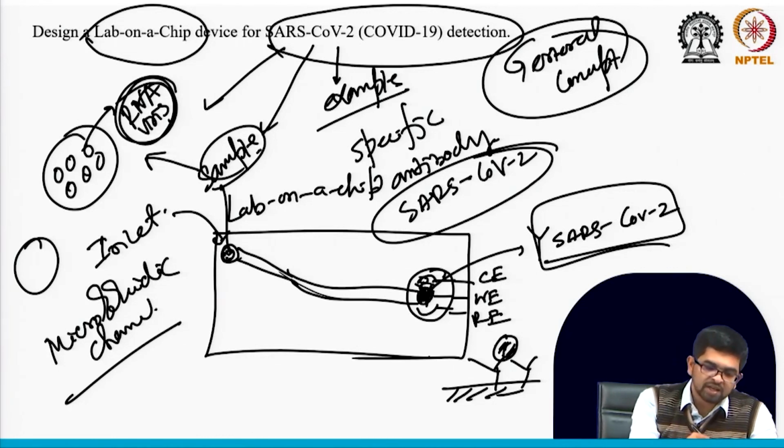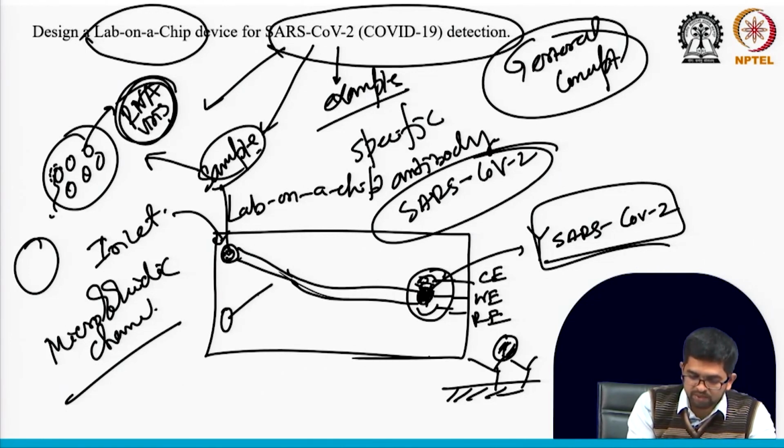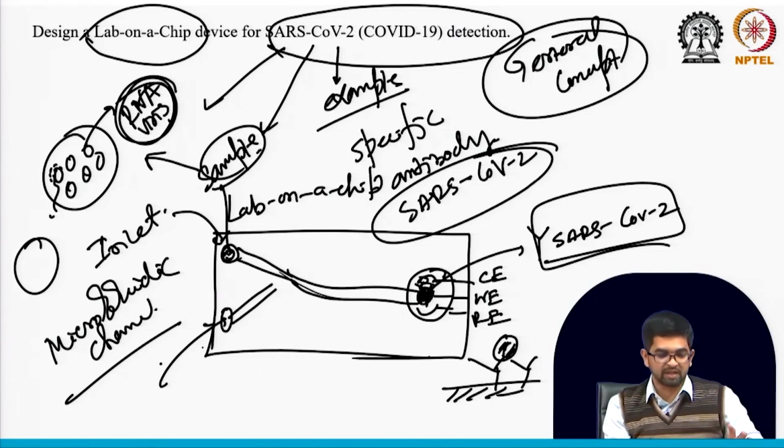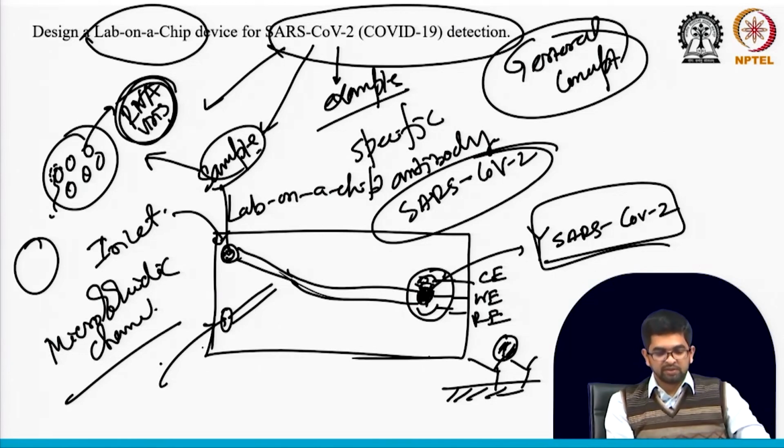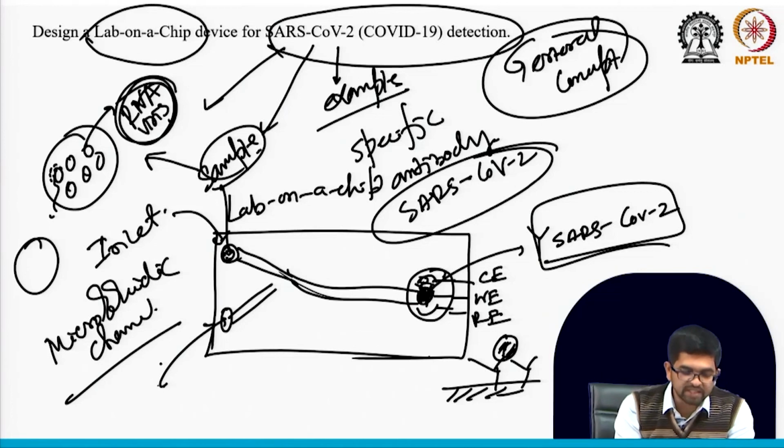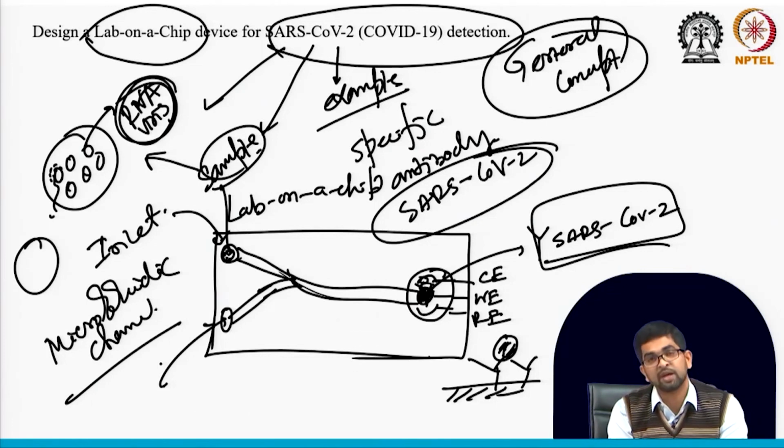So in this case, the upper part of the virus has to dissolve, so that you may get that RNA. For that you may have to use some other chemical for the dissolution of this virus. So the upper part you have to dissolve, so some chemical you may need, some kind of surfactant-type chemical that will dissolve this virus. That chemical you can inject here through another channel, so it will then connect with this main microfluidic channel.